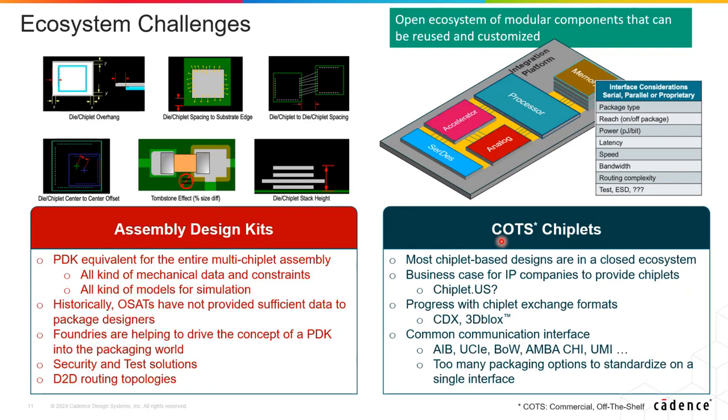It is a very new thing, so we need to consider everything that we need to. And also, in the legacy packages, we just collect off-the-shelf dies or packages and assemble them on a substrate. But in the old days, it was okay just to connect the dies or packages with a relatively large distance, and the interconnection IOs were not that high. But in advanced packaging, the distance between the chiplets or dies should be very close, and the information transfer should be very large. That means we need lots of interconnections, so we need new interconnection standards and methods.